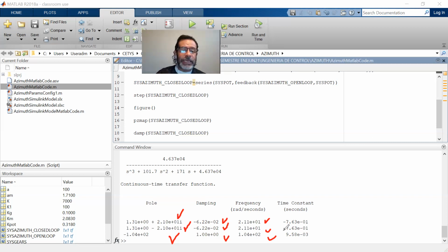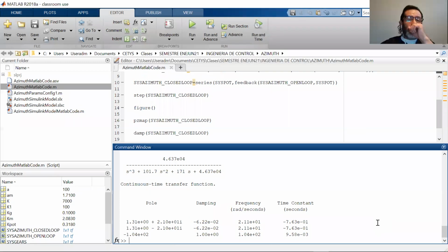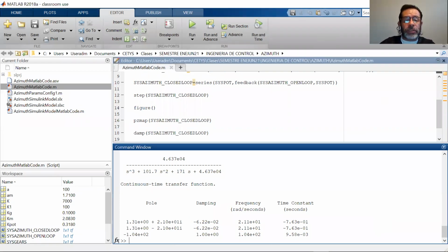So in this case, even though we have one real pole that's negative, that would give me a stable response with a dampening ratio that's positive and a certain natural frequency, this pole isn't the one that's dominating. The poles that are dominating are the ones that are imaginary and are on the right-hand side. If I have any poles on the right-hand side, those are always going to dominate.